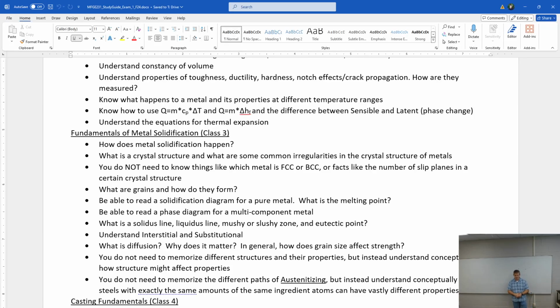What do we have a lot of and not a lot of? A lot of strength, not a lot of ductility, okay? In the hot work region, we have the opposite of those. We have a lot of ductility, we don't have a lot of strength. The warm work region, well, it's just hard to tell. We might. So we can take things there when we do recovery. We can take things there and maybe we can regain some ductility and retain our strength, but we have to be really careful how hot it goes. The closer we get to the hot work region, the more strength we lose.